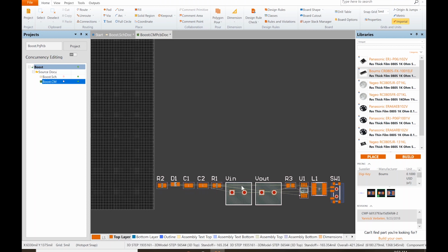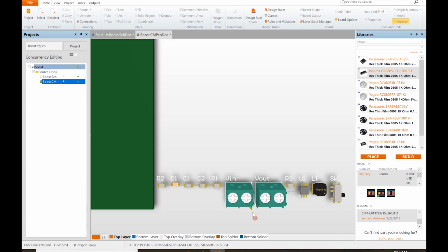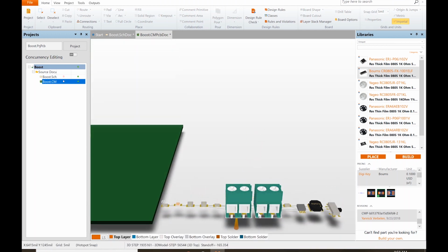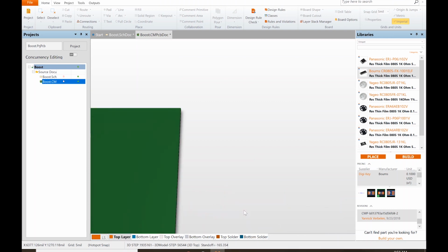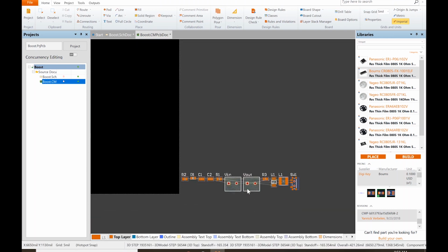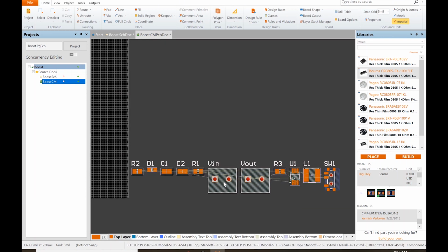Okay, also notice that these components do have a correct position and an incorrect position. They're both facing down, so this is the opening. When I go to the 2D view, I want to make sure that this is pin 1, this is pin 2, and that this edge is facing out.